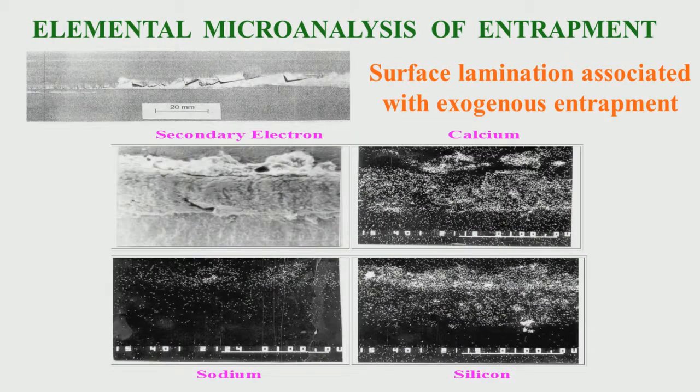So, in this way you can do metallographic analysis, and if you have knowledge of continuous casting, steel making, steel refining, you know whether it is entrapment or whether it is a crack, you know which type of grade you are casting, you know what the type of solidification is. So, you can tell what the possible defects are, at what stage they have originated, and accordingly, if the defect takes place in future, you can take some remedial measures.